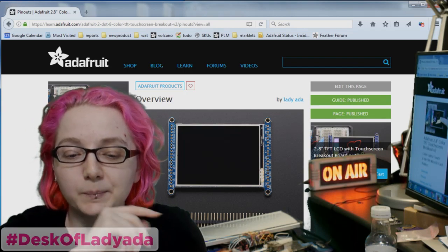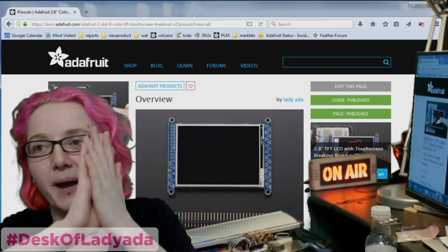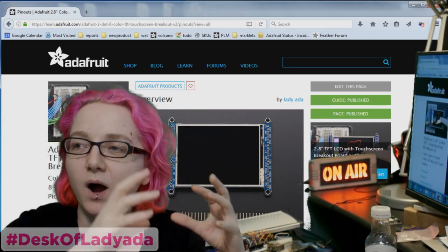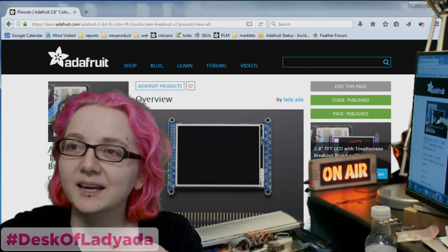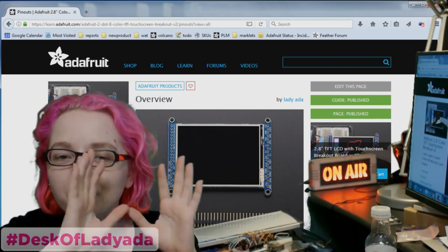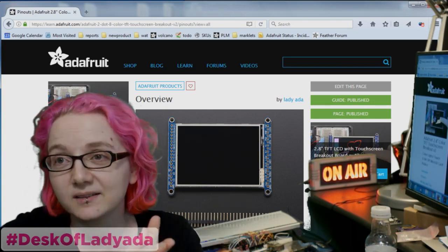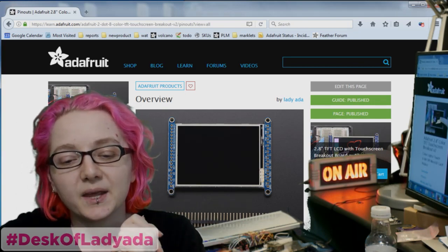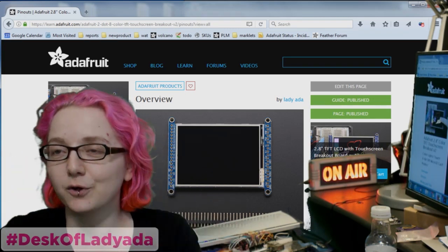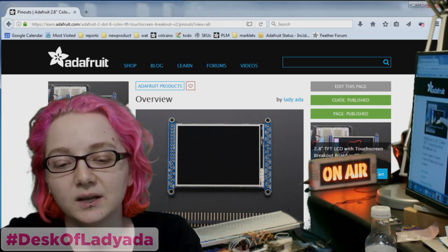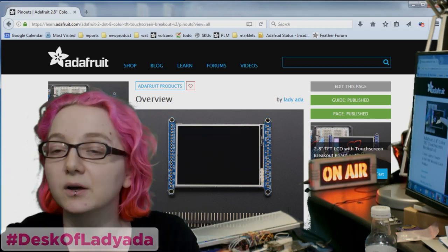I'll show you why you need a stylus. And so we talked about capacitive touch, and the way capacitive touch works is it measures the capacitance of the human body. We are walking bags of salt water. We have some other proteins, a couple of fats, but for the most part we are walking bags of salt water. We conduct electricity not so well, but we do conduct it somewhat, which is why you can get electrocuted. We also pick up RF noise through our salt bodies. And so capacitive touch detects the capacitance of our bodies, which is about 20, 50, 100 picofarads or so.